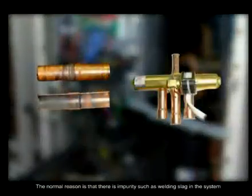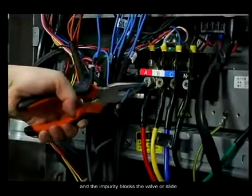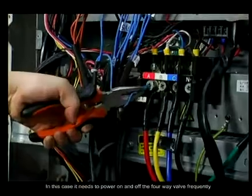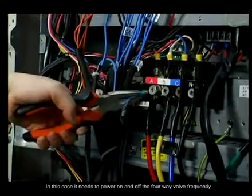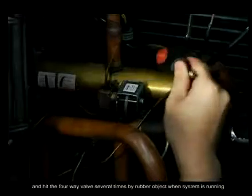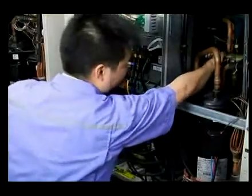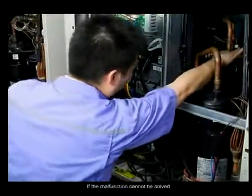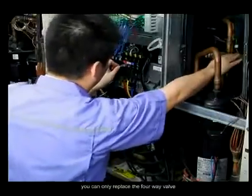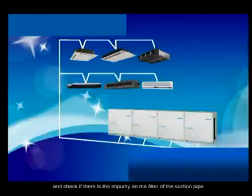The usual reason is that there is impurity, such as welding slag, in the system, and the impurity blocks the valve or slide. In this case, you need to power the four-way valve on and off frequently and hit the four-way valve several times with rubber objects while the system is running, so that the slide block can be moved by the refrigerant's momentum. If the malfunction cannot be solved, you can only replace the four-way valve and check if there is impurity on the filter of the suction pipe.